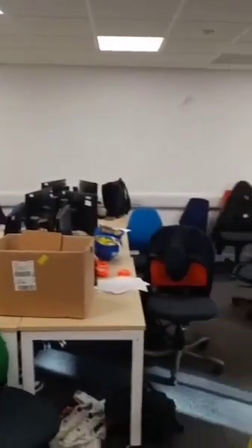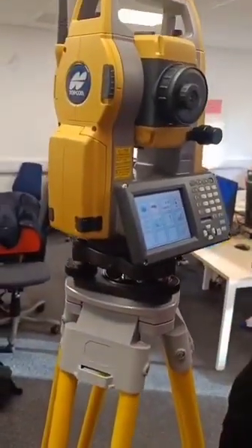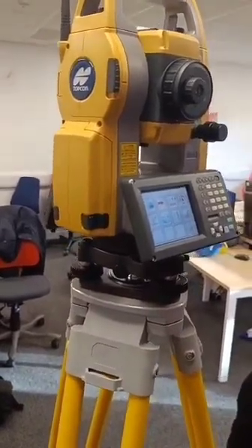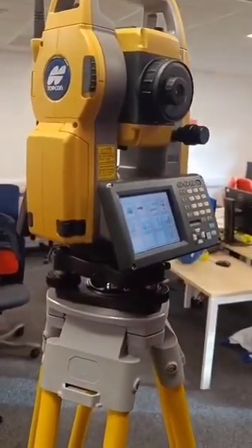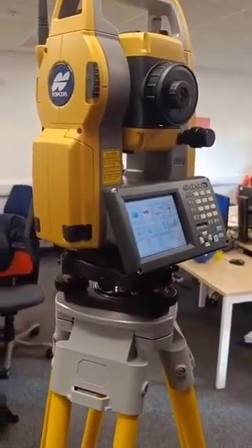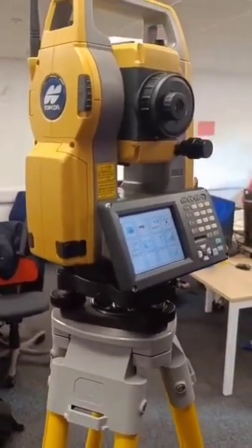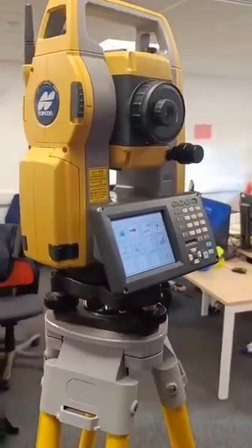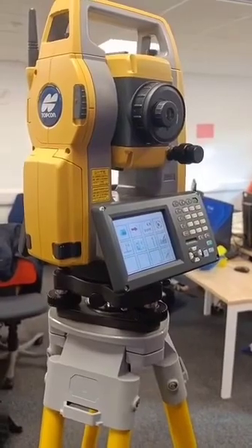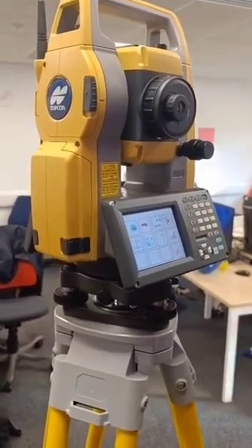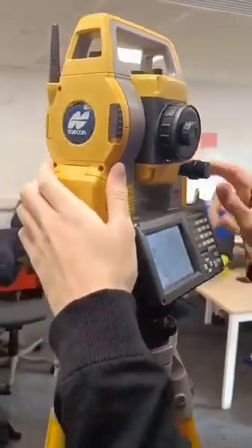And so for your backsite, you'd choose a point that normally wouldn't move. When I was doing my survey, I chose a very specific nail in a corner of the thing. It doesn't matter too much in your exam, because they're not going to check what you use as your point that much, but it is just the general idea, something that doesn't move.